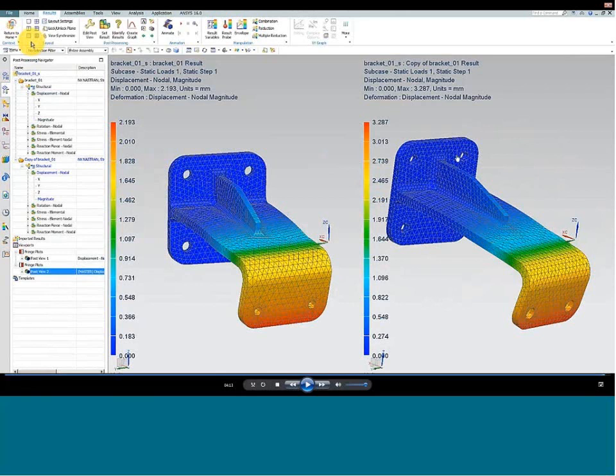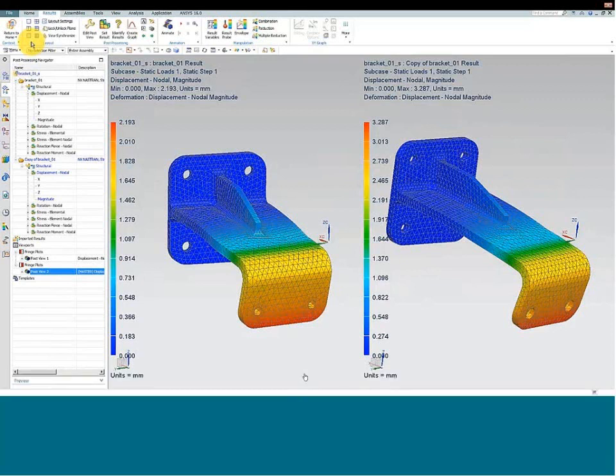The point is we're now in a position where we can take nodes and elements, associate them to some representative CAD geometry, and then leverage these very powerful synchronous modeling commands to reshape the mesh and to pull and stretch these elements in such a way that their quality is maintained, but they reflect design changes or design updates that we make, and now we're in a position where we can perform these very rapid trade studies without wrestling with mesh updates or any of those things that happen when you work with finite element models by themselves without any associated CAD geometry.